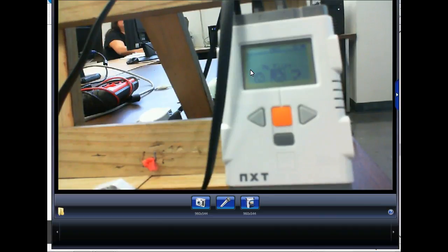To get the full-blown capabilities of this robot, we'll primarily use offline programming. Y'all understand the difference? So what's online programming? Yeah, at the robot itself. And offline programming is what you're doing with the robot. You're writing your programs over here, developing your programs on your computer, and then you take it from the computer and upload it into the robot controller.